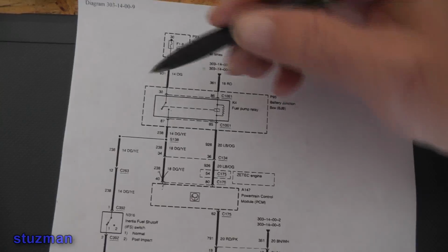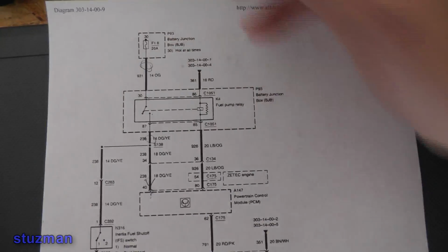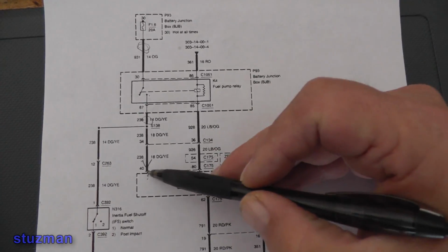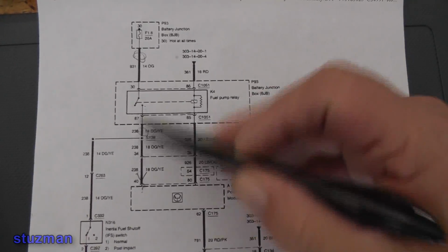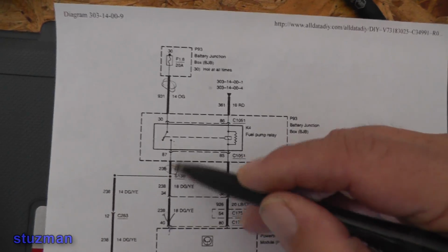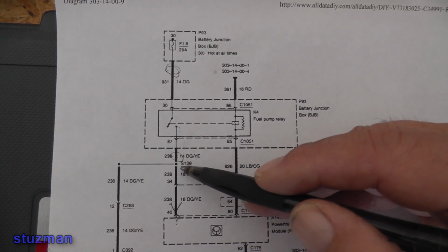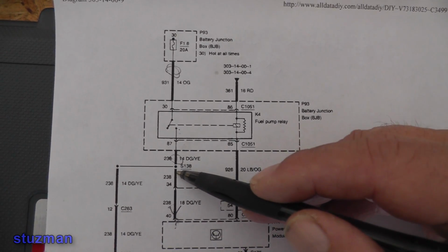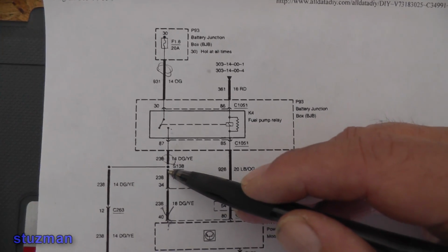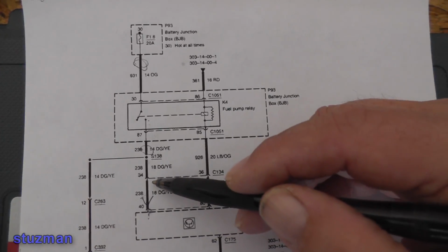So we can measure our current here, we can measure it here. Now, of course, we will get this little tiny bit here, but it's negligible, so we don't care. My point is that you want to see what is on the fuel pump's circuit, because you may be feeding, say, injectors, ignition coils, or some other loads, and those are going to be substantial loads.